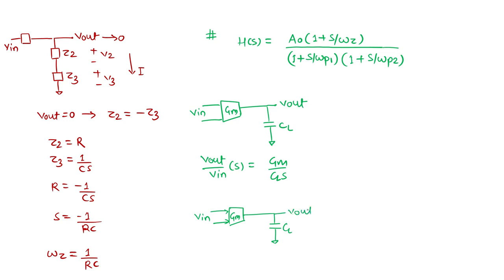So this is the load that I want to drive, and this is the inherent property: yes, R naught is there as the output impedance of the GM cell. Then what transfer function have we seen? We have seen V out by V in equal to GM by G naught divided by 1 plus CLS by G naught. So this thing we have seen.